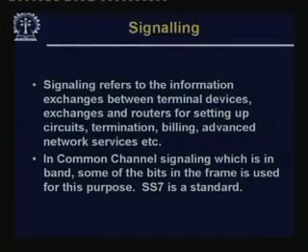Okay. Codecs stands for coders and decoders, and there are various coding and decoding standards, but anyway, it will have a bunch of codecs which will convert the analog signal which is coming through this local loop into a digital signal, and then this digital signal is ready to be multiplexed with other digital signals to reach its final destination. Okay. Now, a little bit about signaling.